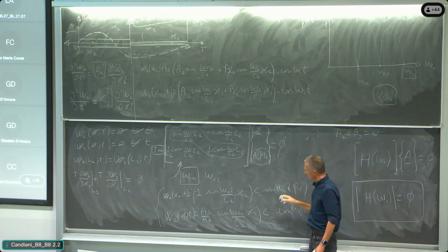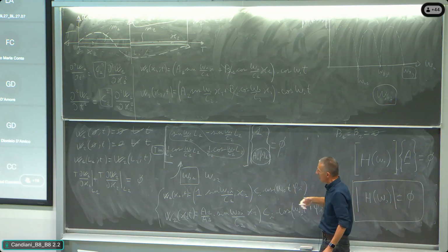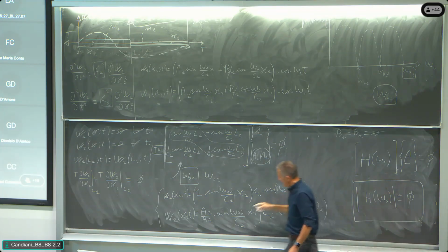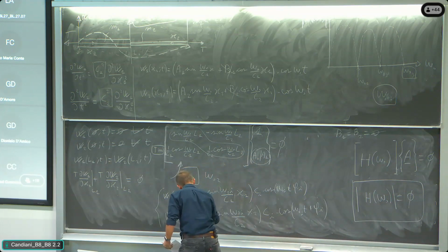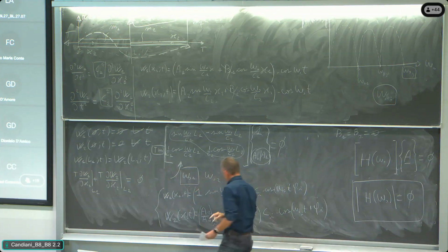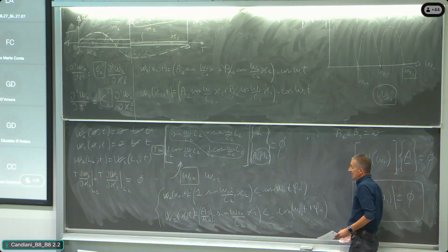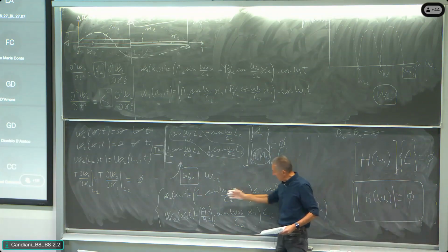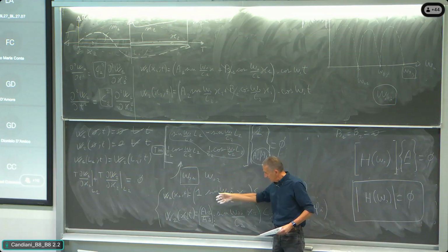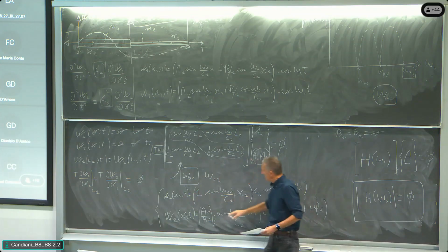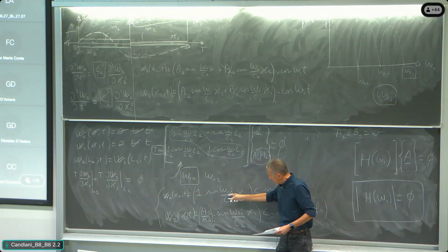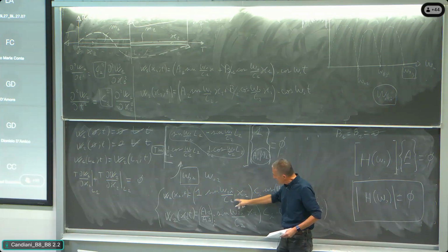And so we write that with whatever omega 0 i, we have a ratio A2 divided by A1 that is index i, that is specific of the ith mode that we are looking at. And then we have a shape function that is a sinusoidal function for the domain 1 that is made by the omega 0 specific of the ith mode divided by C1 multiplied by x1.